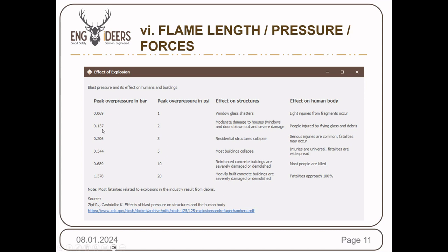That's why if you would apply such a dust collector inside a house or inside a factory, this would not be allowed. This is also part of the standards. So you would need to use different explosion protection systems like flameless venting or suppression to account for this. Or you can also use a vent duct, which directs the explosion to the outside through the wall.